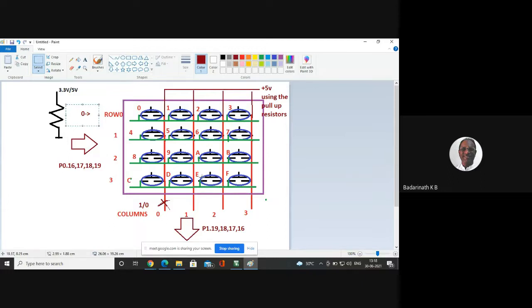For example, if you press the E key, I can generate the ASCII code for star. I can generate the ASCII code for the enter key. Something else I can generate. So it depends upon the programmer what key code he can generate based on the physical location. For this program, I have numbered the keys 0 to F in a contiguous way. So if this key is pressed, I should generate the ASCII code of E. So what is the mapping required? Physical location to the ASCII code you have to generate.